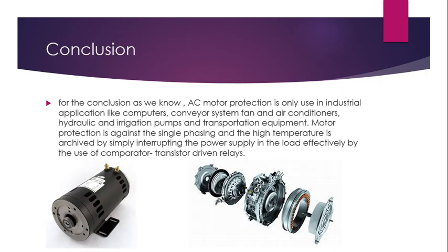Okay, for the conclusion, as we know, AC motor protection is used in industry applications like compressors, conveyor systems, fans and air conditioners, hydraulics and irrigation, pumps and transportation equipment. Motor protection against single phase and high temperature is achieved by simply interrupting the power supply to the load, especially by the use of a comparator transistor driven relay.